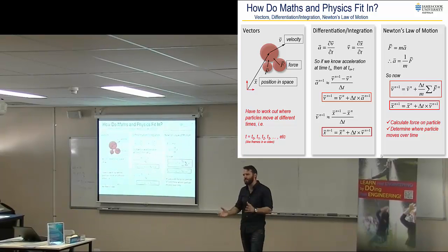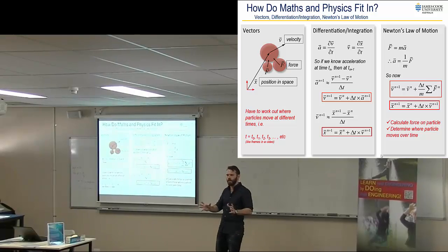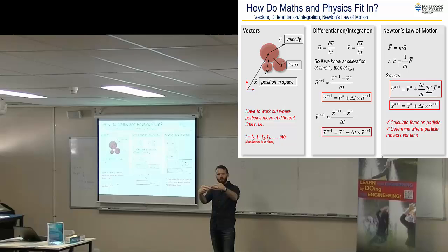That's one of the main distinguishing factors between a particle code, an FEA code, a fluids code or whatever: what type of forces are applied. In a particle code, the forces might be gravity, and it might be two particles coming into contact with one another. You can calculate the force by knowing where this one is and where that one is, and if you say they're elastic, how much they're overlapping, and you put in an equivalent spring for that overlap. If they've overlapped by 1 millimetre, you imagine that they've compressed by 1 millimetre, and you apply that amount of force.